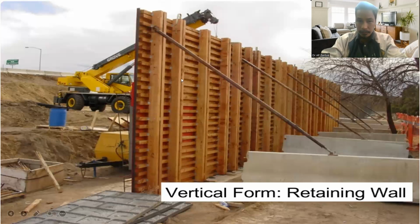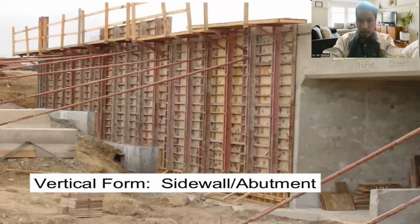So this portion is actually our formwork, and this supporting post or supporting diagonal structures, they are what we call Falseworks. Okay. So we are following what? The ACI 347 standard. So same is true when we are going to set up a formworks for side wall or abutments, for bridges.